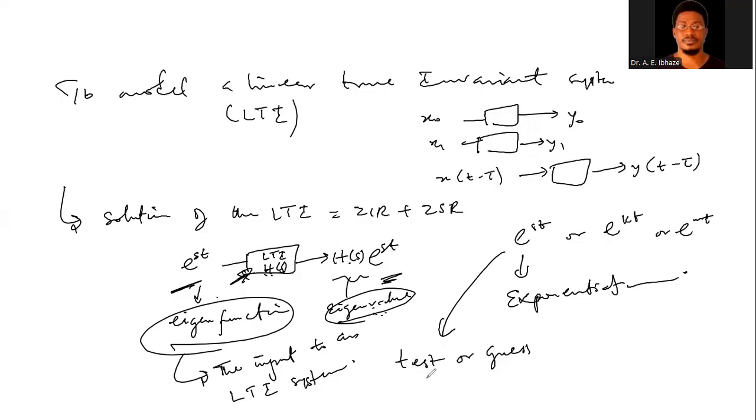That's by the way. Now, we're trying to address electric circuit systems. So I've been able to establish the fact that we use the exponential function as a test or guess signal, largely because should we differentiate this parameter, we're going to get the same parameter. So should we feed e^(st), the exponential function, into a system as the input, we're going to get a replica of that at the output, only that it should be scaled by whatsoever parameter we have in the input.